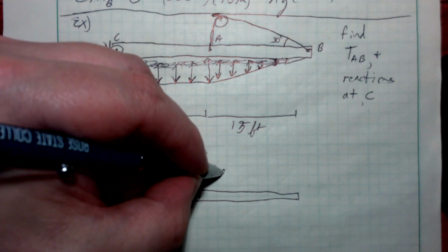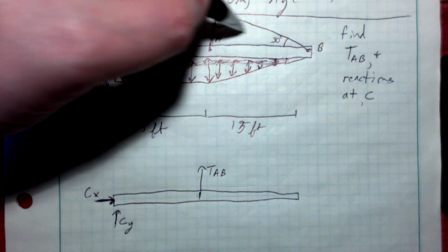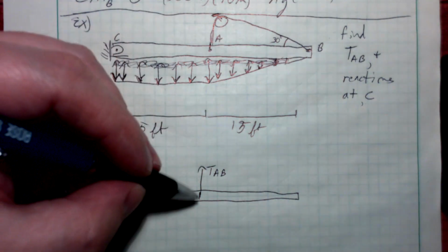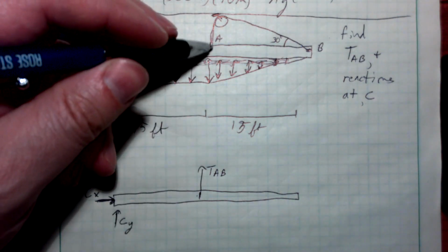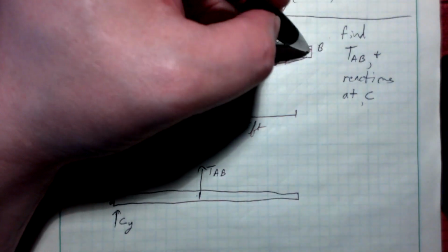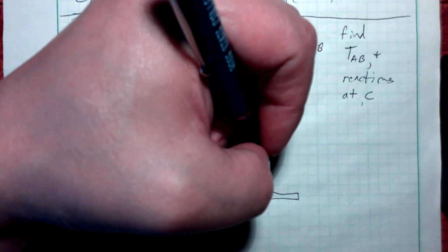All right. So I've got tension AB. Again, it's this cable up here that runs across this pulley and back over here. So it's the same cable all the way through, so it's the same tension in that cable all the way through. Here it's vertical, so I'm removing a cable here. So I need to draw a vertical pull force right there. And then I'm removing a cable down here. It's at an angle. You can draw it TAB here at an angle of 30 degrees.